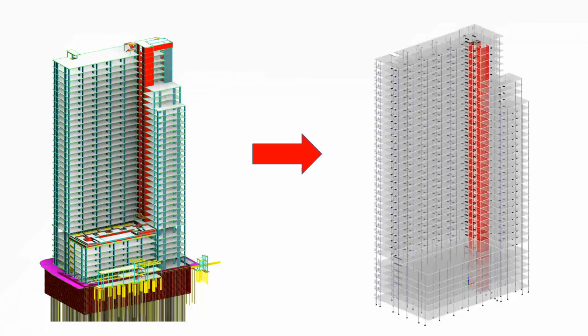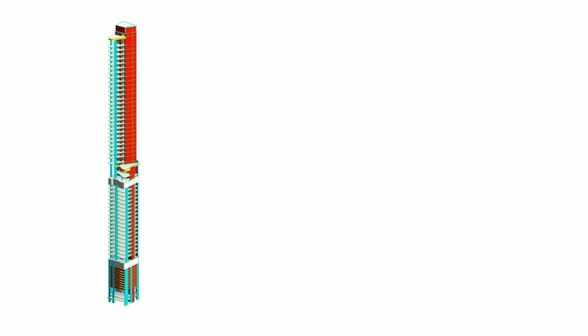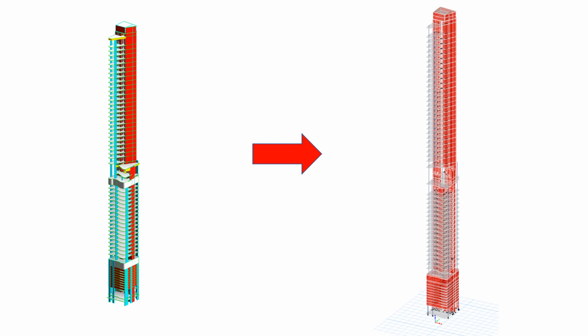Remember that a Revit model is composed of volume-like geometry, which is considered as 3D elements, while the finite elements we need are 1D or 2D elements, which are line and shell elements. Because of the dimensional difference between those two, the Revit model cannot be accurately translated into a usable finite element model without proper understanding and preparation.